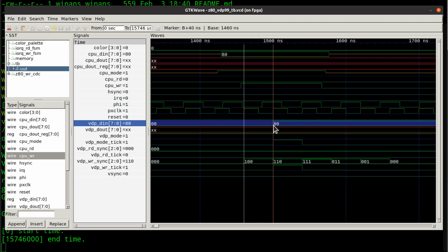Normally what you do in a synchronizer is create your 3-bit shift register type of thing, and when the second 2 bits have received this pulse, so this whole thing about this metastable thing that could occur on the first bit in your shift register, what you see down here, it goes from 000 to 100 here, because it saw this go up.